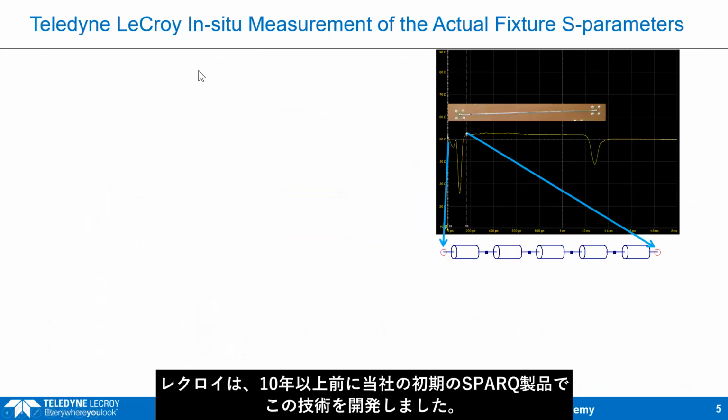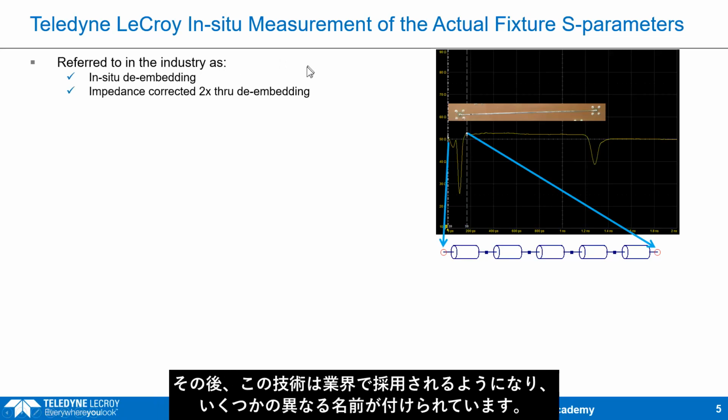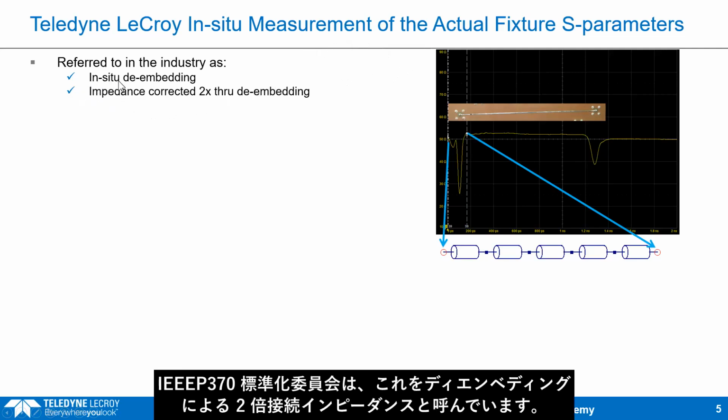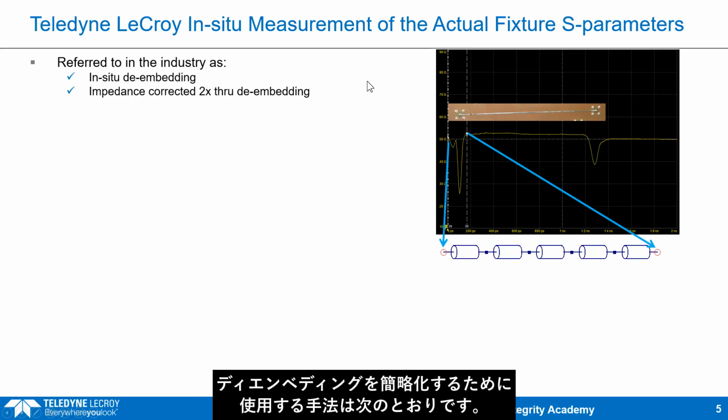LeCroy pioneered this technique more than 10 years ago in our early Spark product, and it has since become adopted in the industry and goes by a couple different names. Some folks refer to it as in situ de-embedding. The IEEE P370 Standards Committee refers to it as impedance-corrected 2x through de-embedding. Both of these techniques refer to exactly the same thing. Here's the technique that we use in order to simplify de-embedding.